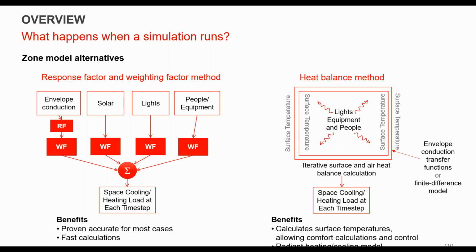And then once it enters the space, there are, again, for all the other loads, including envelope, weighting factors. And those are simpler, but similar to what the response factor is, but it's accounting for the actual thermal mass of the total interior space. Since now the heat has entered or has left, you have a load in the space now. So this accounts for the mass of furniture and the interior walls and the roof and the floor in terms of how long it takes for those loads to show up as actual loads on your coils.